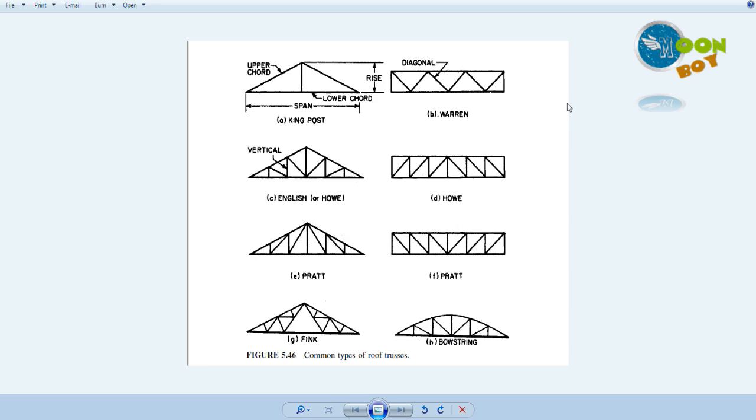So I'll be selecting the auto select option for the truss members, and it will be selected automatically by the program, and after design we will be selecting this as auto. Then after designing, again we have to analyze one more time so that we can get the correct sizes and economical sections of the truss members.